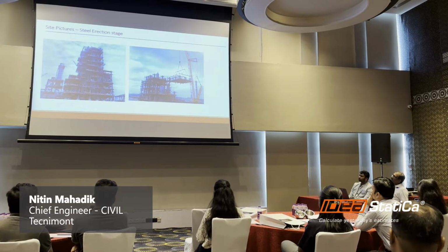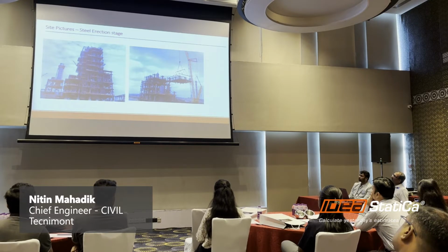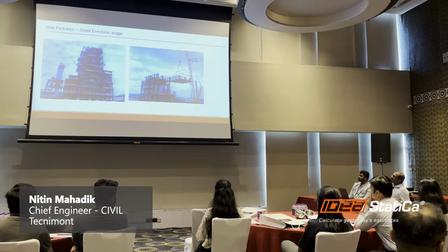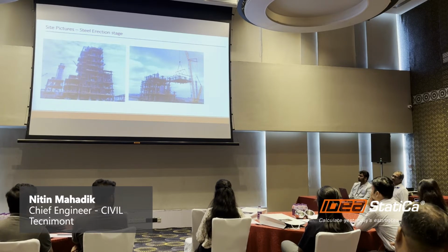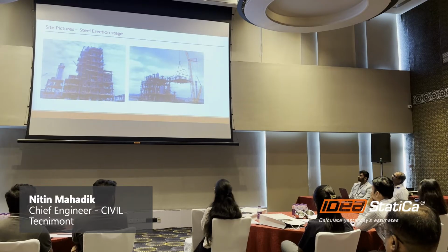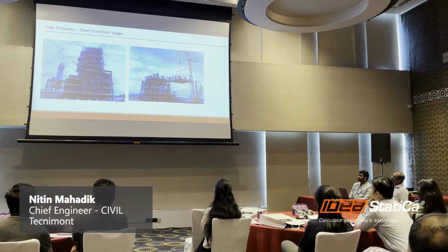And here we have implemented one philosophy to erect it in modules, like pancake modules. You can see the complete floor is erected, and the pancake which is being erected there is assembled on the ground with all the beams, columns, grating, handrail, ladder, and small miscellaneous equipment, and the complete module is erected in a vertical sling position. So each floor is one pancake, a pre-assembled module lifted, and this reduces the erection time substantially, and this is being implemented now onwards on all the projects in Tecnimont.